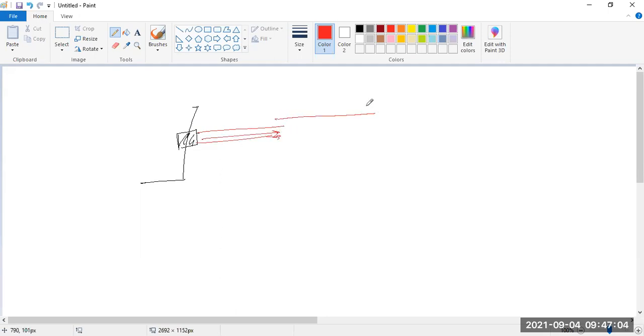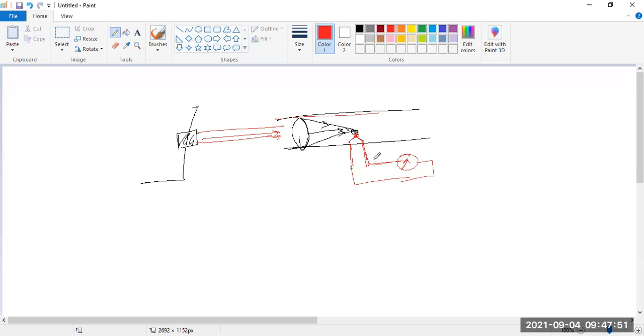Here, first, in a pyrometer, there is a lens. But this type of lens, we have to set a focus on a particular area, so that it is focusing on a focal point. Now, in this area, a thermocouple or an RTD, or any temperature detector like a thermistor, we can put over here. We generally use a TC because a TC directly gives the measuring signal. So in this way, there is no optical portion.